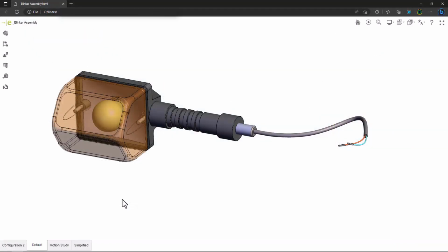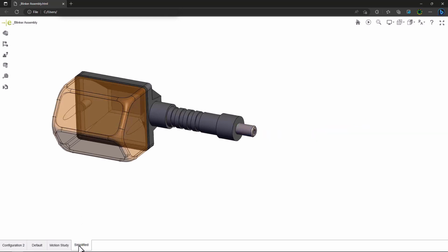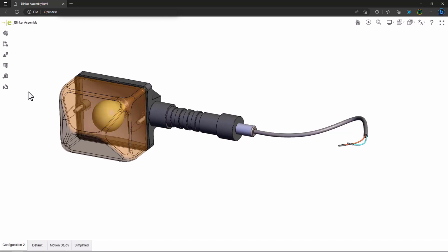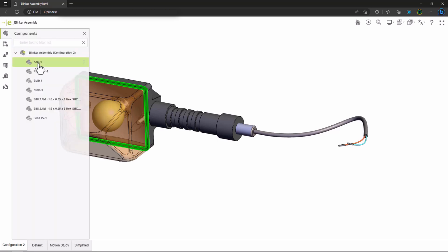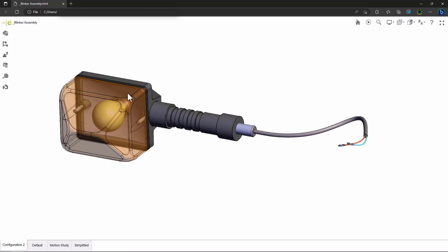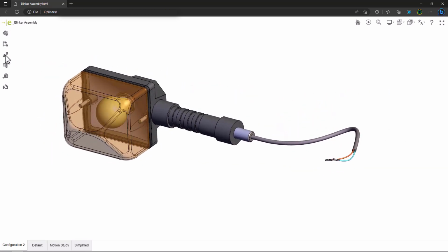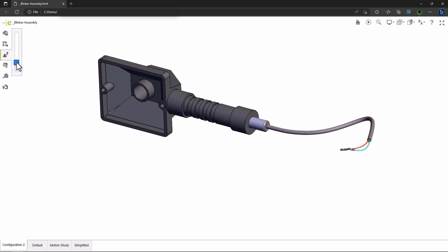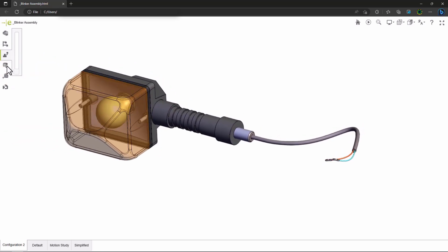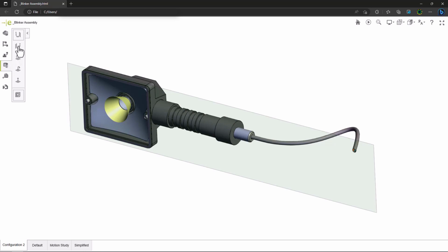First, eDrawings Professional introduces the ability to export web HTML files, which can be hosted on your network or online and viewed by anyone with an internet browser. No installation required, no ActiveX, not even the eDrawings viewer. Web HTML files have nearly the same functionality as eDrawings, but don't support stored animations or 3D views or simulation data or exploded configurations or markup. So there are a few limitations.